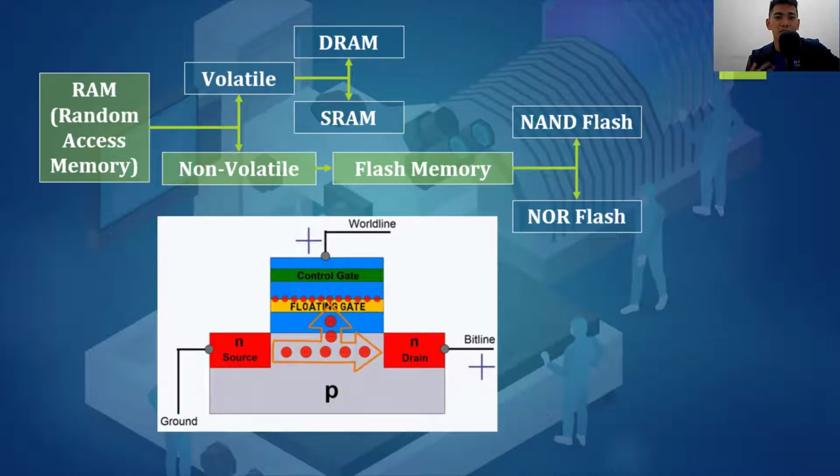Flash memories, which essentially consist of floating gate MOSFETs, are currently being used extensively, particularly for embedded applications due to their low cost and high density. The basic principle is that a specific threshold voltage is applied on the word line for each control gate of the floating gate MOSFET, so that you can arrange these transistors in parallel or series and control their logic states.